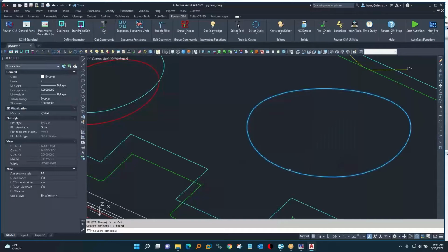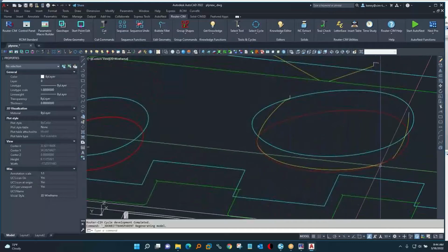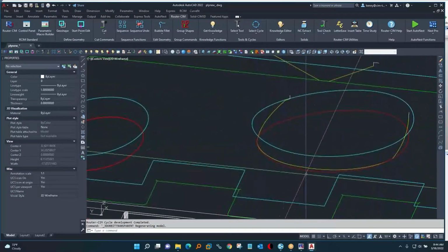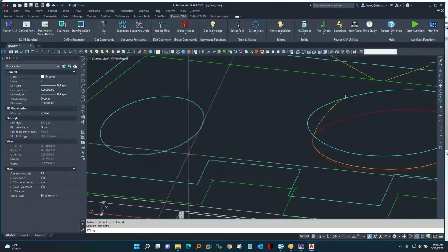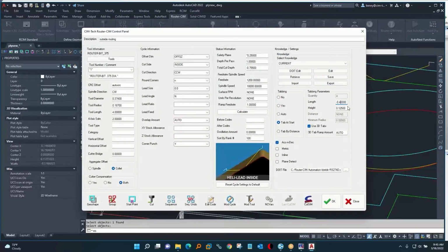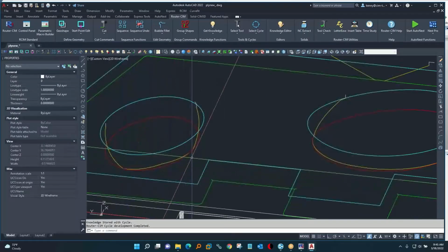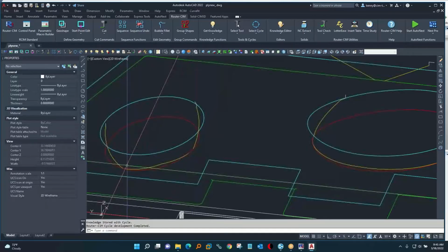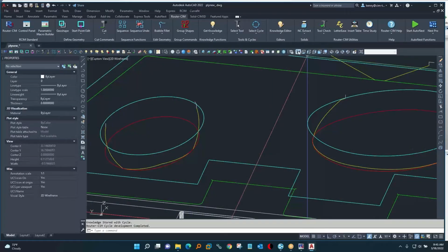And when this makes a cut, this leads in and right away makes a tab, cuts around the shape, then the overlap cuts the tab off. So that's 1.5 times around the part is what I put in there. Here's 1.25, for example. I put in 0.25 for this. Cut this one. And again, you can see what's going on. It leads in, leaves a tab, and it's a ramp tab. Ramp up, ramp down, not lift straight up, burn the part in the tool, and plunge straight down. So it's a ramp tab, cuts around, then the overlap cuts the tab off.